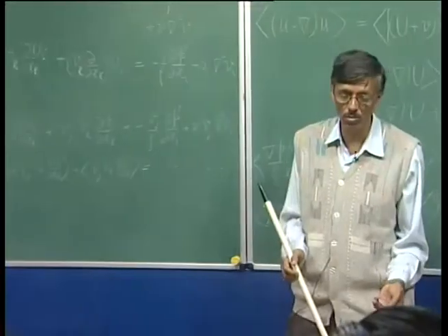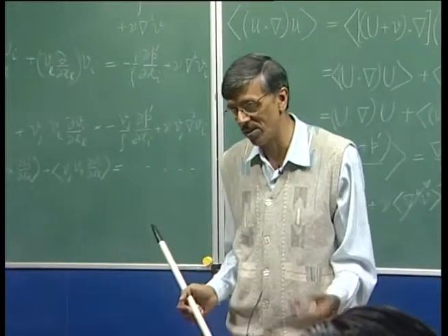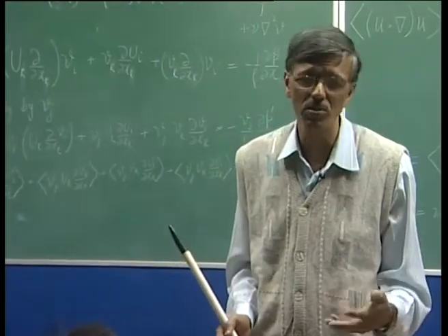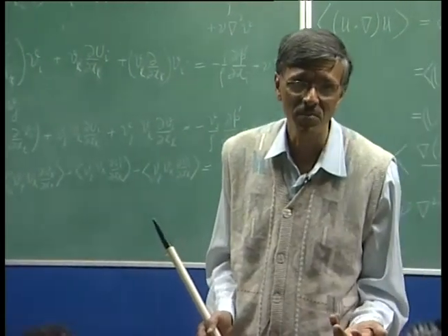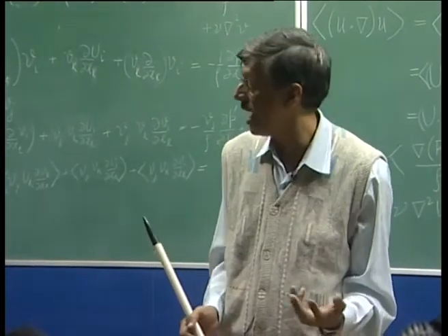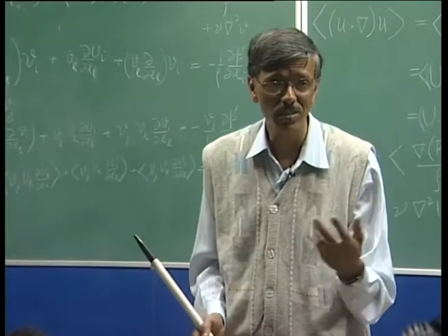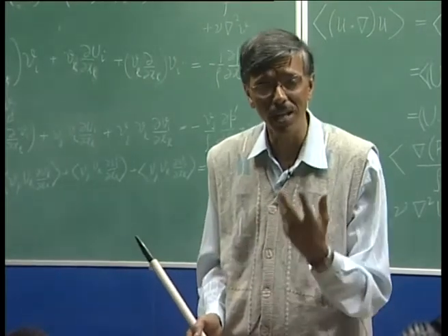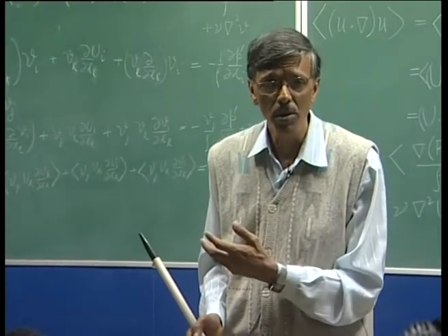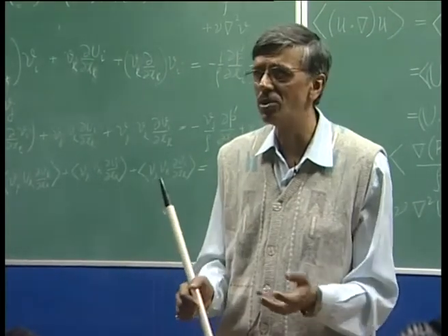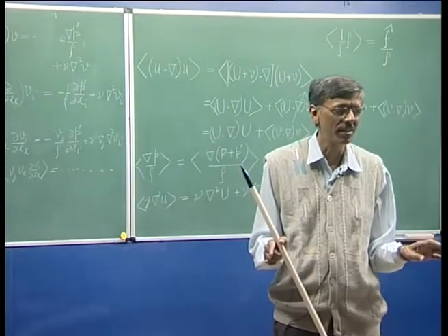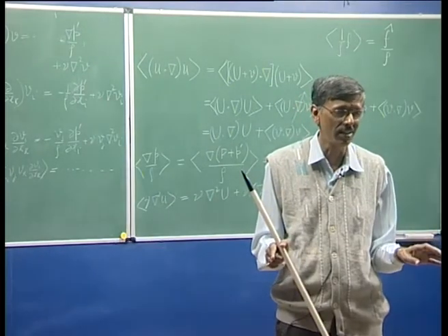In fact, there is a major activity in turbulence modeling where people do write down this equation for Reynolds stress directly and try to solve it. But please do remember that in writing those equations for the triple correlation term, they need to do some kind of modeling. It is not a priori that you are going to get a completely analytic solution.